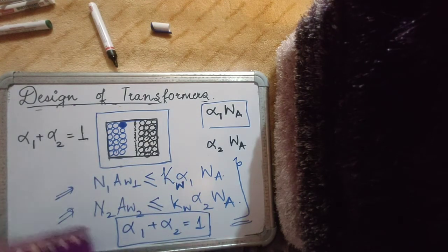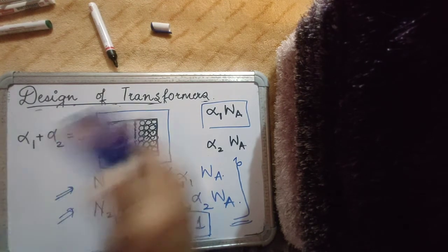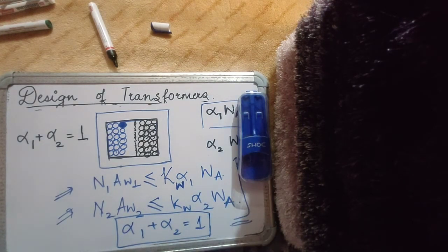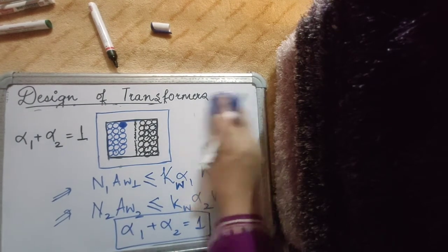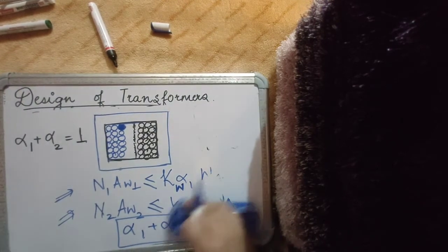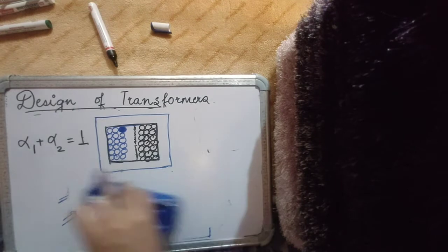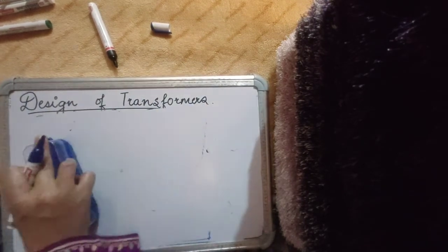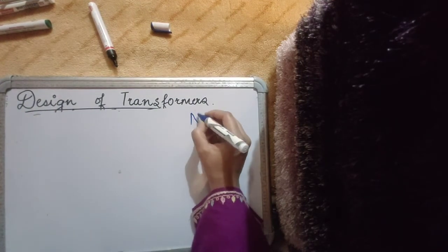Apart from that, we have another constraint, which is on the copper losses. And I have already discussed with you while doing inductor design that the copper losses will depend upon the resistance of the windings, right? So let me simply write the sizing equations on the right hand side, because I may need to use them again.